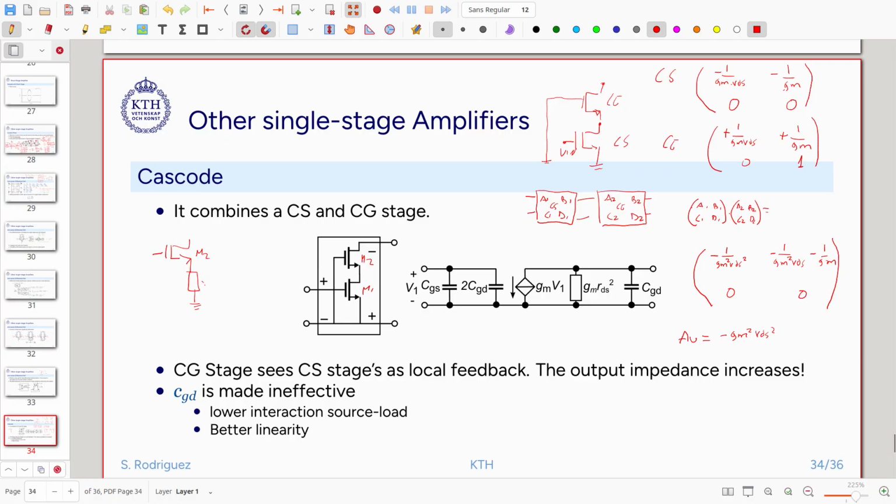That is a resistor, and that is going to be RDS1 here. And we'll talk a little bit about the loop gain for this transistor. The loop gain for this transistor is gm times rds approximately,